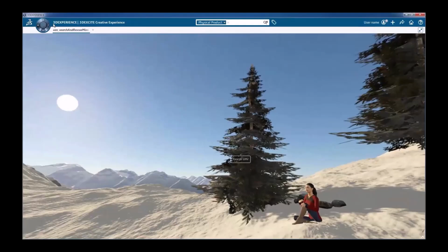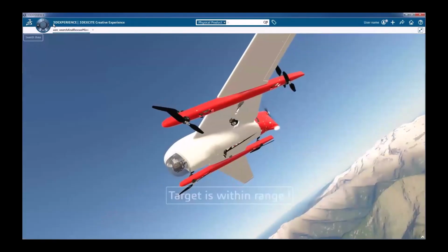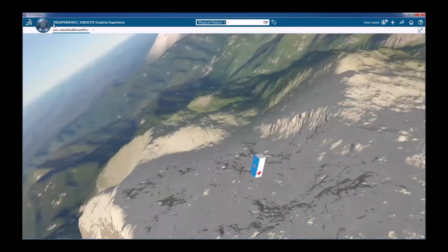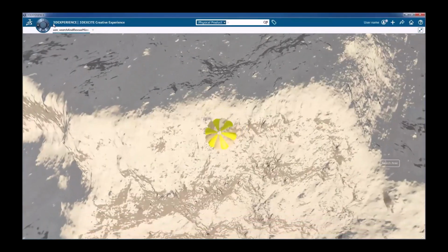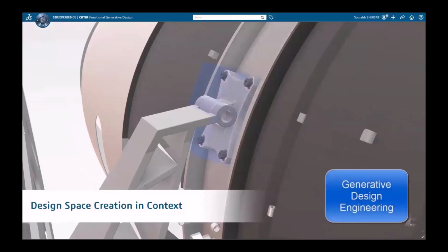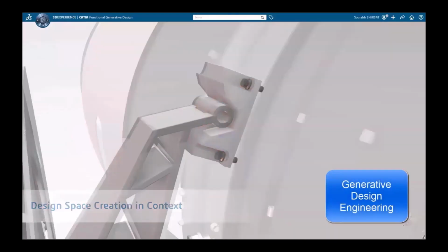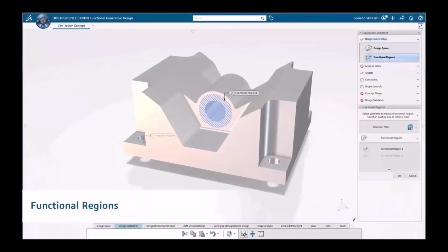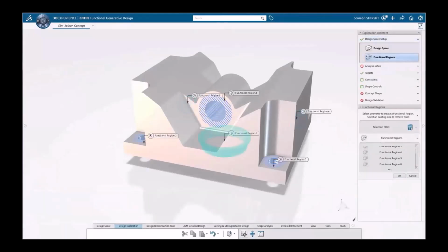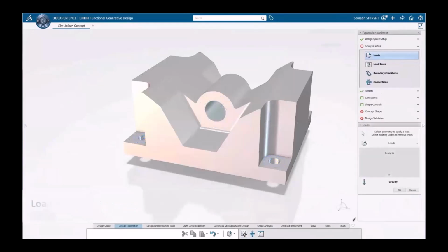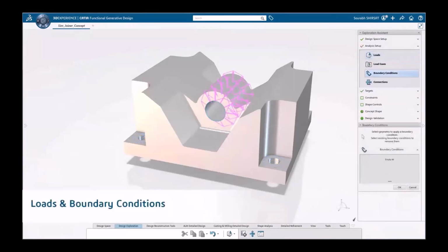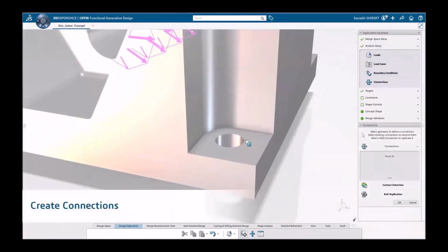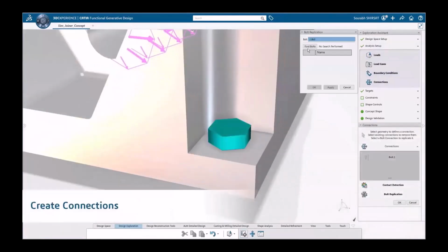And of course, as I told you, this is just the surface. We have really applications for any kind of need because really the platform includes all the technology from Dassault Systèmes. This is the generative design. So you create, let's say, a basic shape. You create the constraints, you put like a goal, reducing weight or maybe avoiding certain resonant frequencies.